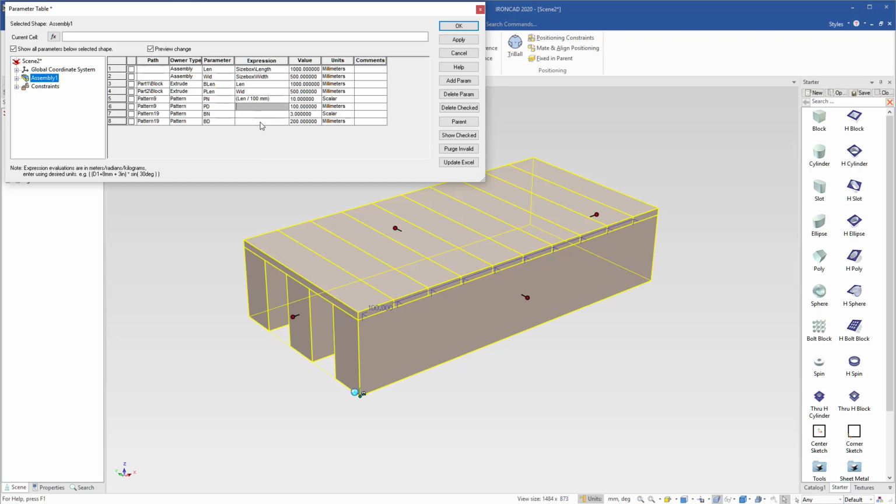Okay, next we need to go and do our pattern spacing for the bottom boards. So we know the total of this is just a mathematical formula. We need to know these two distances here to calculate the spacing. So we need to subtract 1 and divide it by 2, essentially, is what the formula is. So we're actually going to go into our board distance here. We're not going to change our numbers. It's always going to be 3. We just need to calculate the spacing.